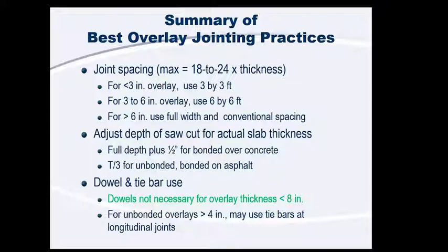It really kind of depends. Your joints are going to depend on the type of overlay that you're doing, whether it's bonded or unbonded, especially if you're doing bonded concrete overlay on concrete. Those have some specific joint details and joint requirements that you'll want to look at before considering doing bonded concrete on concrete overlays.